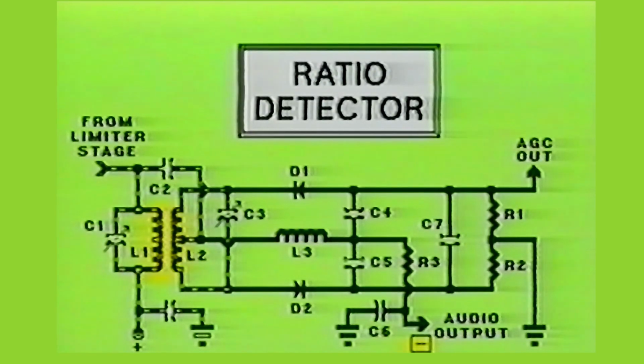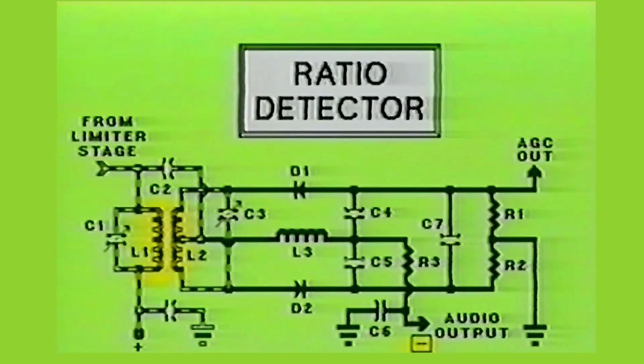Keep in mind that even though the two halves of the circuit are out of balance, capacitor C7 looked at the average power of both halves of the circuit and maintained a reference voltage potential.